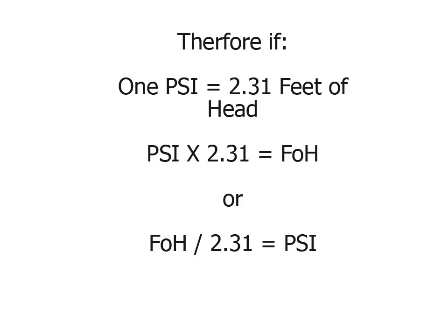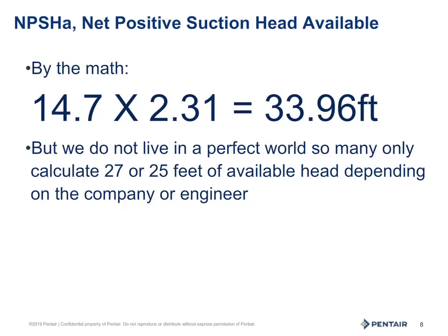This also means if I have a 40-foot pipe, any diameter, and I have 2 feet of that pipe in the water to ensure I don't break vacuum, and I manage to pull a perfectly sealed vacuum at the top, the water would rise 33.96 feet. In a perfect world, 33.96 feet. But no one lives in a perfect world.